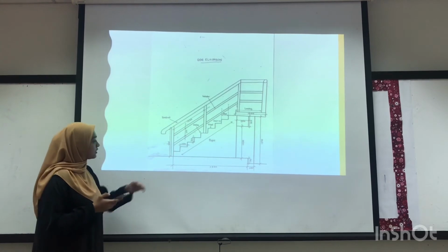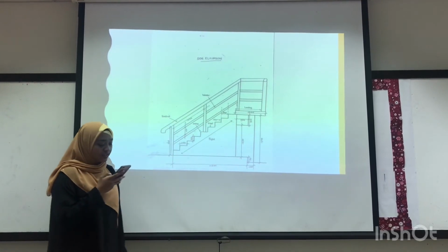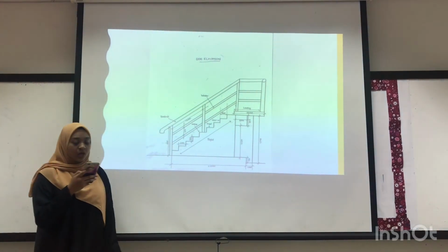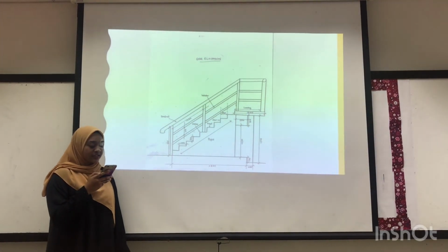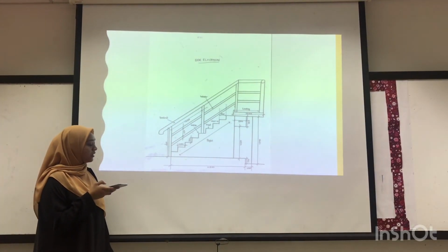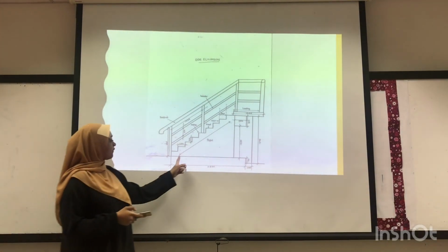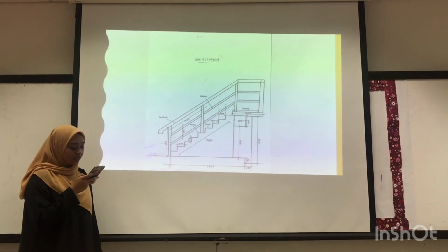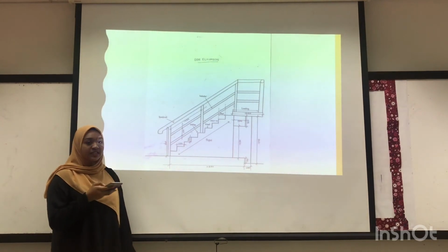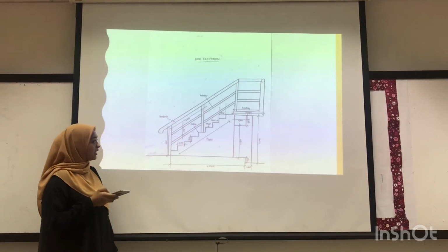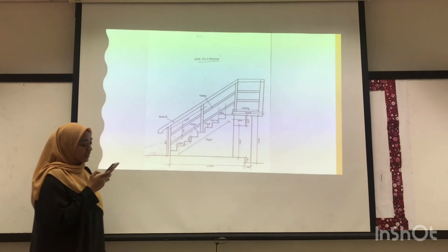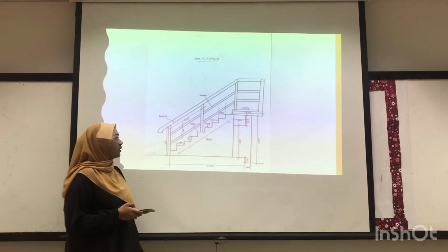The riser, this is the riser. The riser is the vertical portion of the step which supports the tread, size 190. And this is the flight. The flight is an unbroken series of steps between the landings, and the size is 2,600 millimeters.